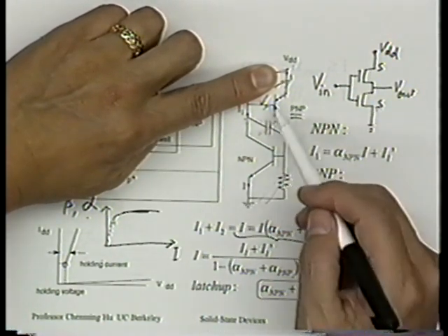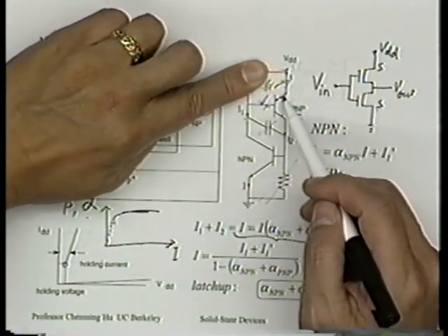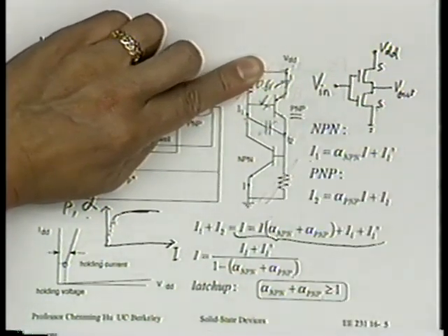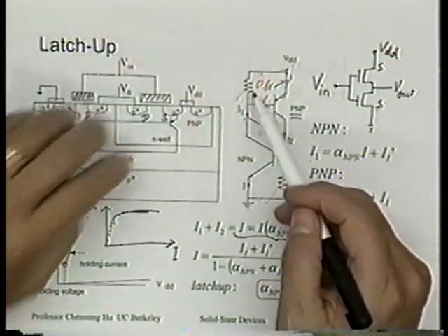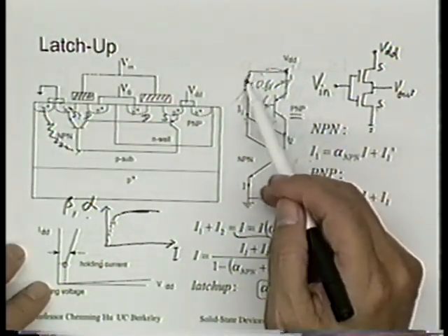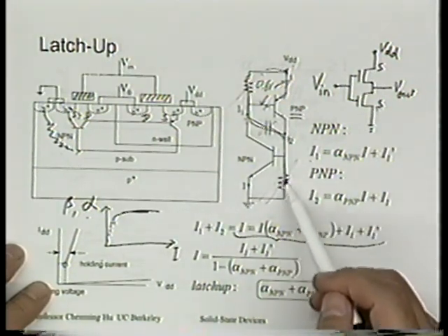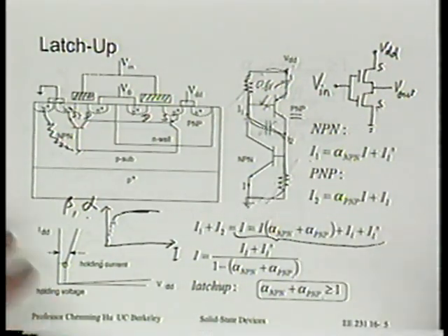Any current flowing through the base emitter junction will mean there's a forward bias, right? And that's what causes this latch up. But if this current can flow through this lead path, you see that? Then there will be no problems, yeah? It's okay? So that's the example of how this helps with this one particular trigger mechanism.